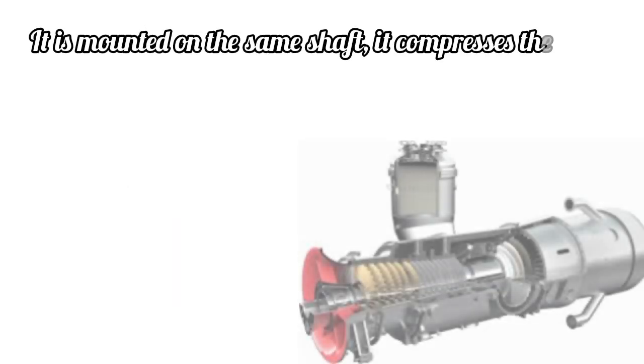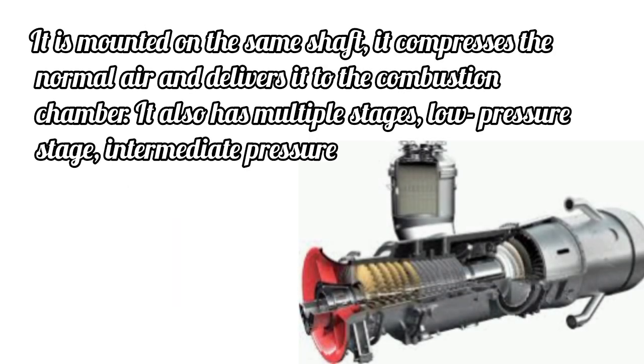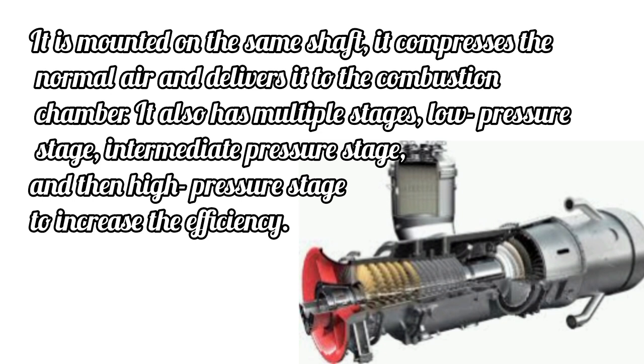Compressor. It is mounted on the same shaft. It compresses the normal air and delivers it to the combustion chamber. It also has multiple stages: low pressure stage, intermediate pressure stage, and then high pressure stage to increase the efficiency.